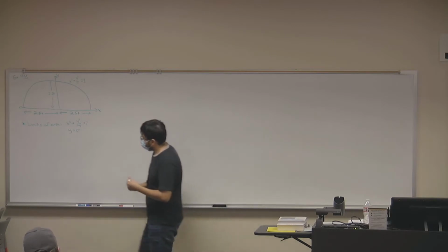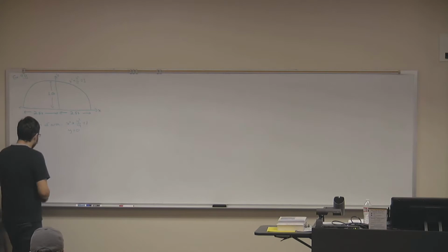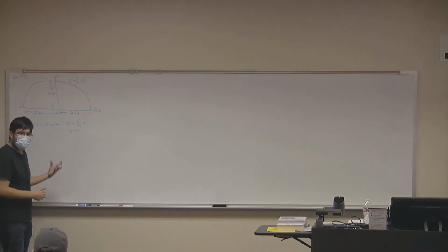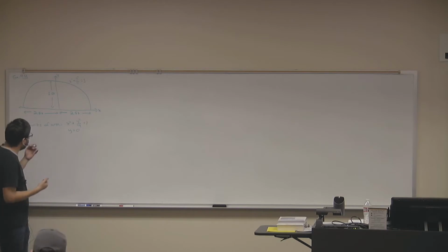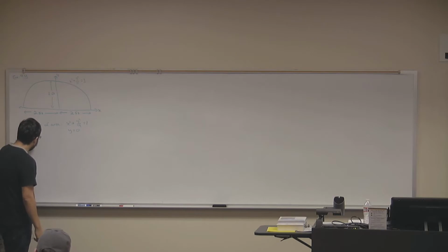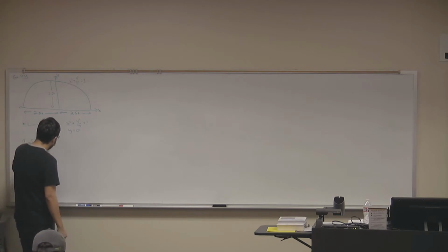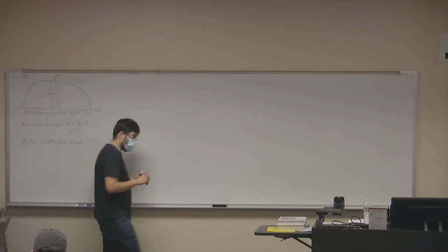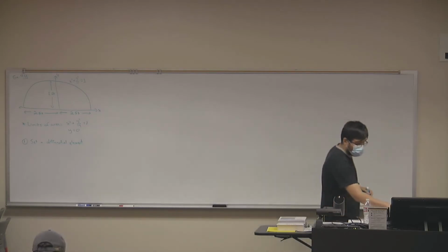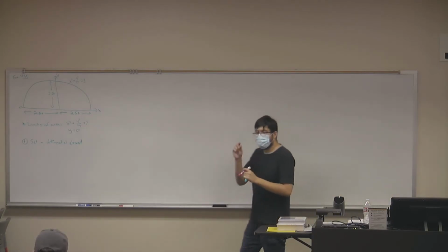So let's start. I mentioned that I don't like these recipe-style examples where we do step by step, but I make an exception for centroids because really the steps for determining a centroid are pretty much the same regardless. So I already mentioned last week that you want to start this problem by setting a differential element. Now in 1 dimension, that differential element will have a differential length dl.